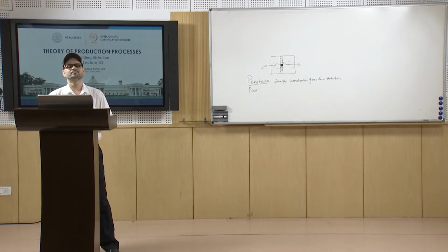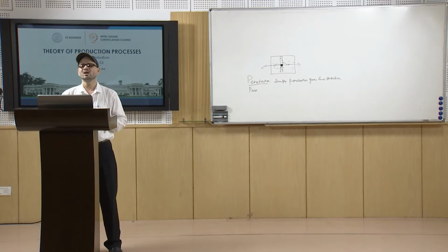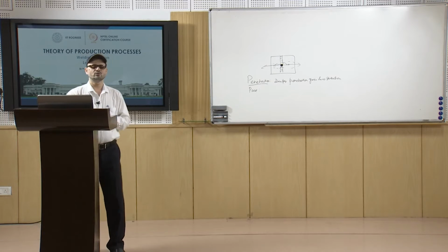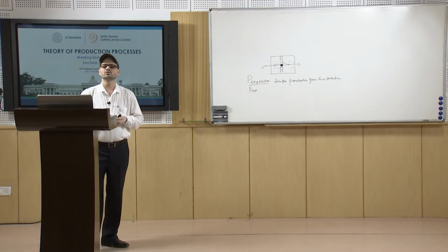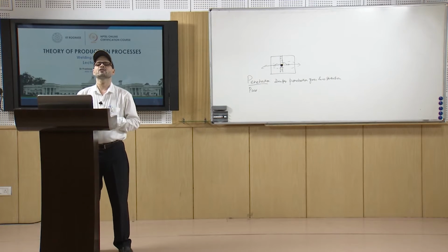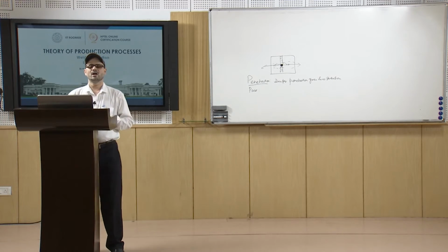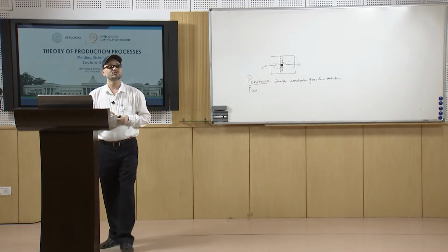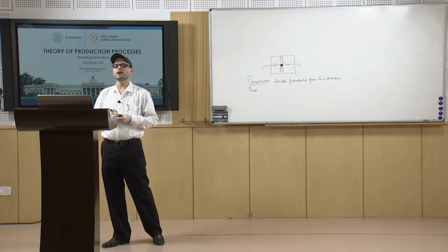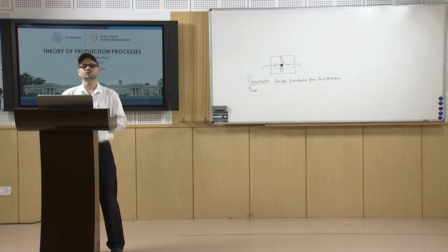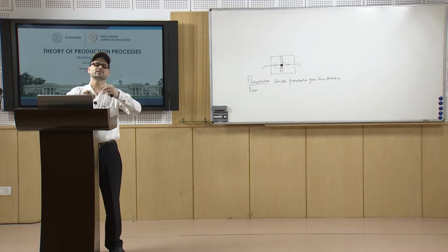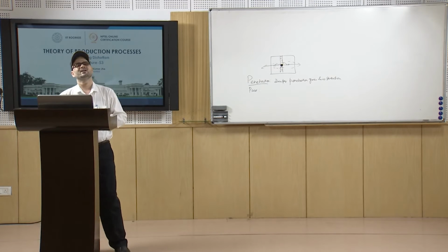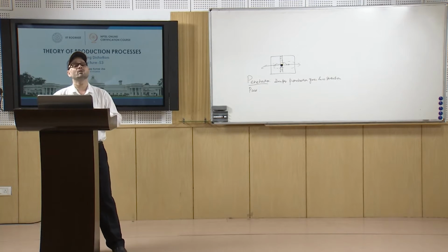Similarly, you will have certain fillet welds also. In the case of fillet welds, you have the restraining cross section area and the weld metal cross section. Based on that, this longitudinal shrinkage will vary. For fillet welds, it will be directly proportional to the weld metal cross section.